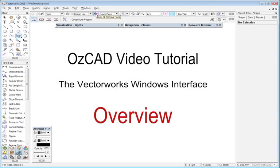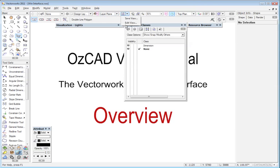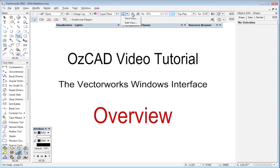This button here is look at working plane. This one here allows you to set whether objects are drawn on the layer plane or the screen plane. If you're working only in 2D, then I recommend that you set this to screen plane. Here we have access to be able to save a view, or if there are saved views in the document, these will be listed in this menu here as well.